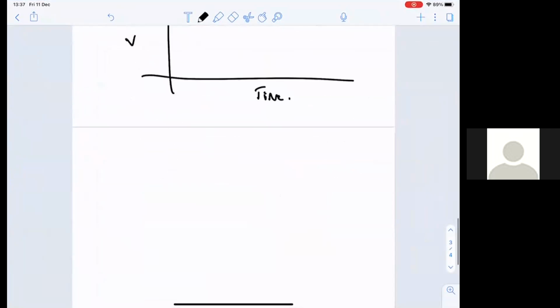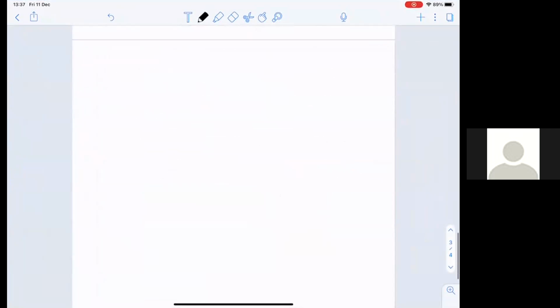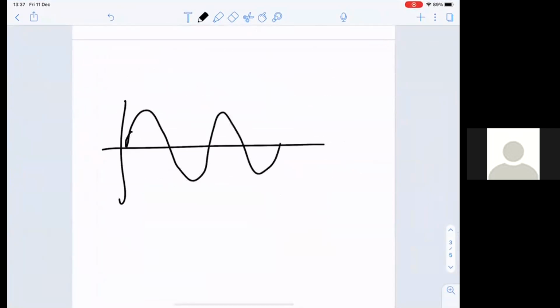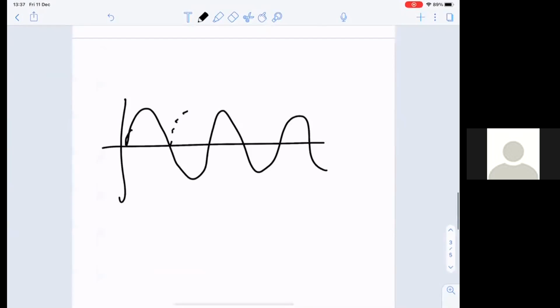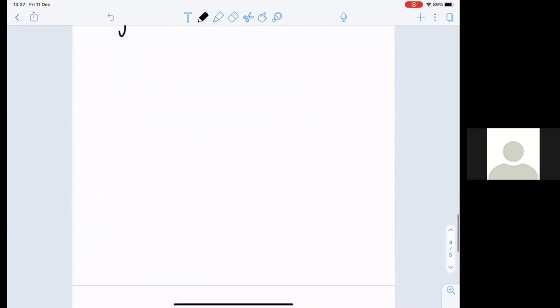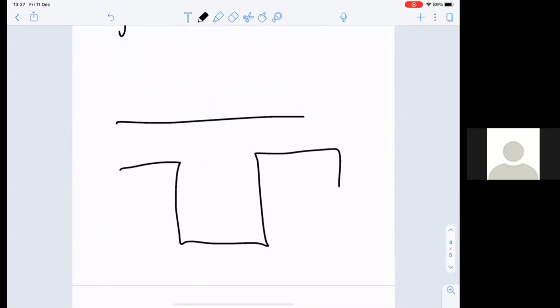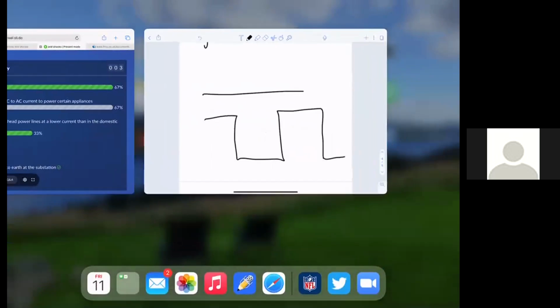Yeah, so a rectifier basically cycles at the same rate as your alternating current and flips the poles. So what you end up with instead of that is this. Just a bouncing positive current like that. So it just flips every one of the negatives up to the positive. And an inverter does exactly the opposite. It'll take your DC current in and periodically flip the poles, flip the direction of current. So you end up with a current that looks a little bit like this. So it becomes alternating, periodically inverting the current.